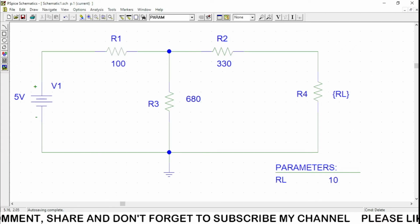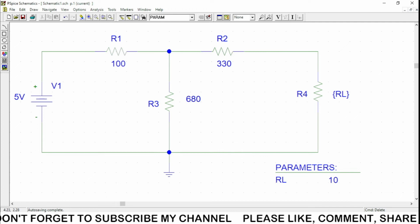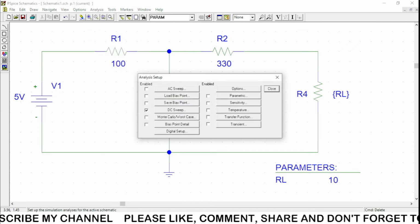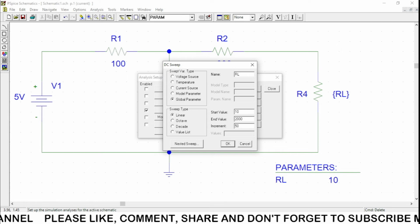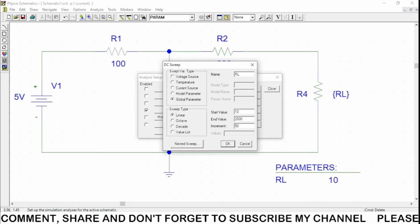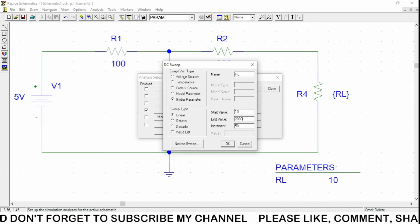Now in the case of PSpice, we can have the same circuit: 100 ohm R1, 330 ohm R2, 680 R3. Here the R4 resistance is considered to be RL. I am doing the analysis setup where I do a DC sweep. Please watch this video in high definition so that you can observe the small font sizes. The global parameter I am taking as RL, start value 10, end value 2000.